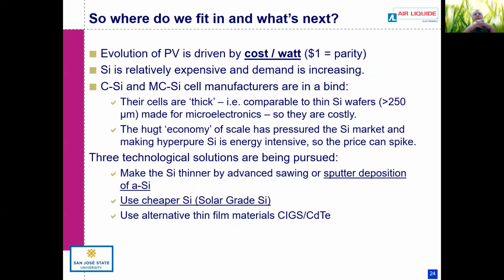But silicon's not a really good semiconductor for this purpose. It's not intrinsically good because the absorption coefficient of silicon is relatively low. It's because the crystal structure of the silicon makes it indirect, so it's kind of like a forbidden transition, the absorption of light by silicon to make electron hole pairs.